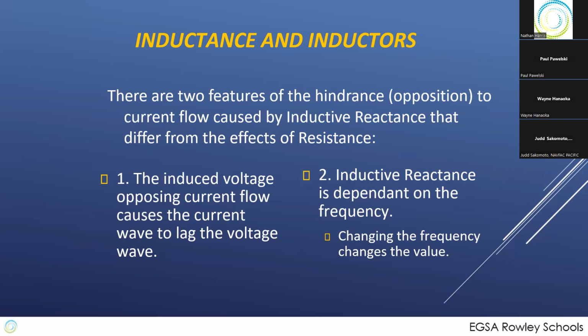Now you see why on the flight line they're using this. 400 hertz means you can use a much smaller inductor with its iron core and get the same results in any radio equipment or radar equipment or anything else in an aircraft. That makes a weight savings. And since both the inductors and the capacitors are smaller, it's a space savings. So this is why you have 400 hertz in avionics systems.